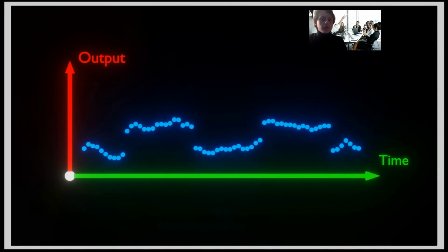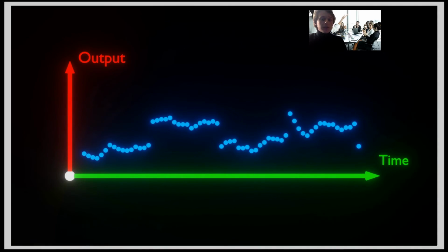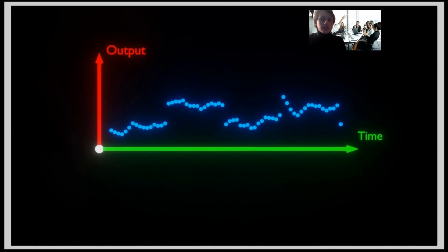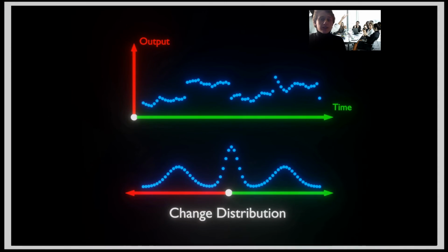The receiver could pick a value and call anything above that a 1, anything below that a 0, but this system would break at locations like this. Instead, the receiver looks at the amount the value changes between each step. The number of each size of change are plotted on a change distribution graph looking something like this. There are 3 bumps on the graph. One is in the center, where all the changes of 0 and all the small changes caused by noise are. And the ones on the outside are the positive and negative changes caused when the transmitter turns on or off.